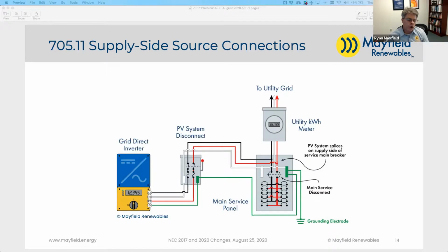Another really hard part of this is, where we're seeing this is typically larger scale, even ground mount systems, where you have a number of inverter outputs coming in and getting combined into a single enclosure, into a single switchboard. What we've seen is the ambient temperature builds up inside that, and with all of those inverters operating, the current is going to be additive into that heat. And so with those thermal mag trip breakers, you may have issues.